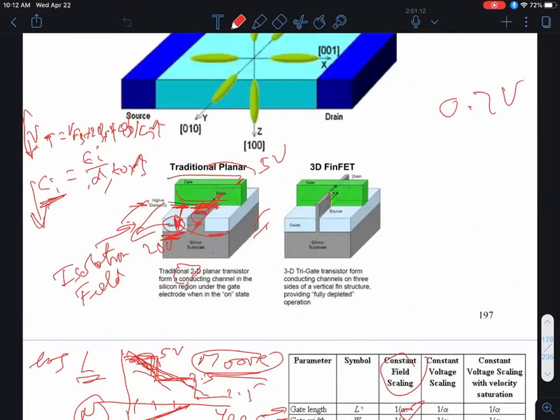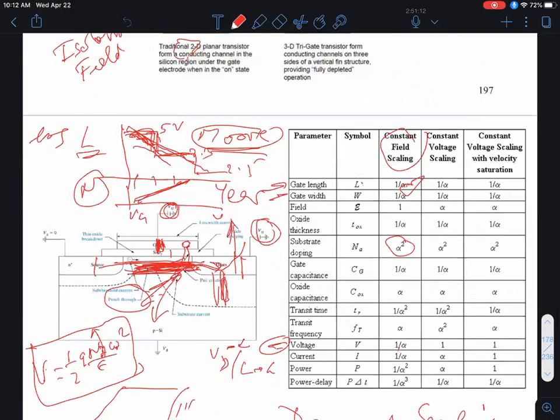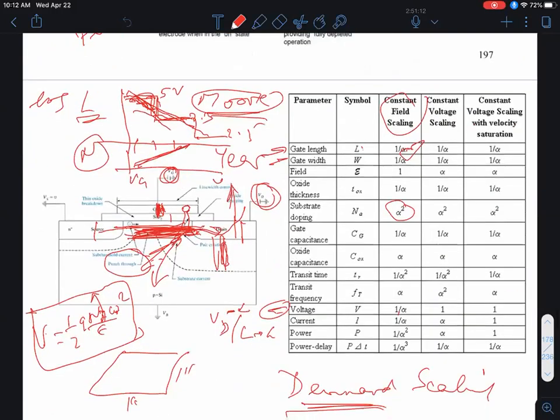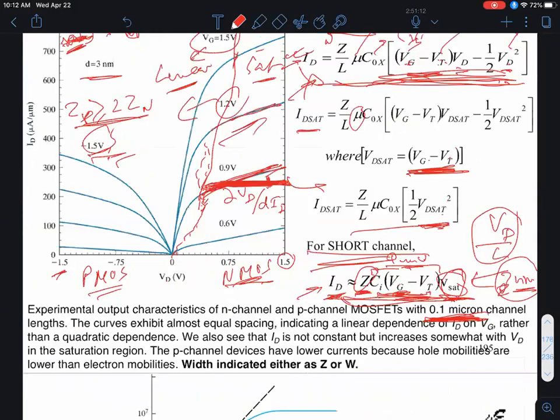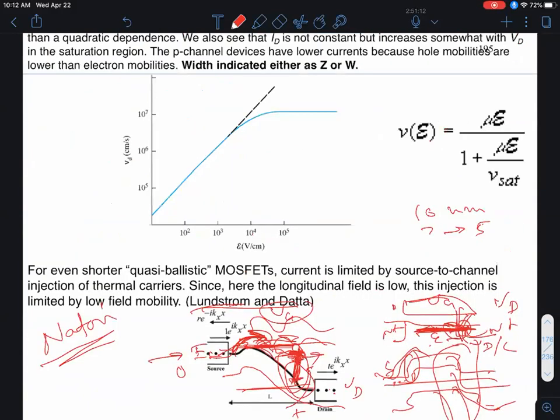So that's what DIBL is. In an extreme case, the drain current can go up so much that the depletion region of the drain overlaps with the depletion region of the source, and that effect is called punch through. The net upshot is the output impedance drops, and the current keeps going up. So how do you think you'd solve this problem technologically?